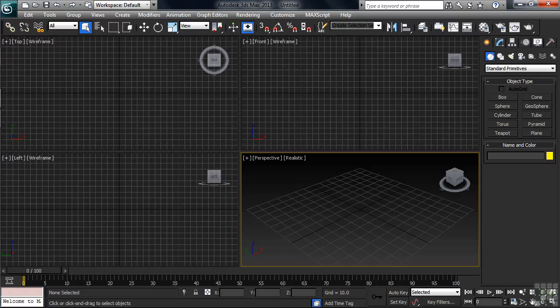Okay, take a look at what's changed. Our viewports are back to their default configurations. All of our snapping commands in the toolbar are back to their off position. And in our material editor, everything that had been previously created has been cleared away. So that's the result of using the reset command. And that's exactly what we'd expect to see, as it's the way the command is designed to work. Reset will be the command you'll be using most often when wanting to start over from scratch.